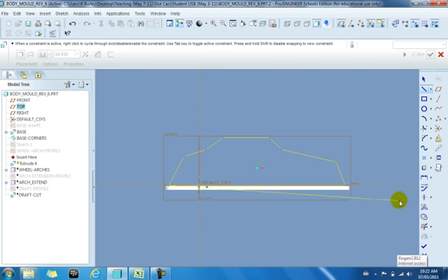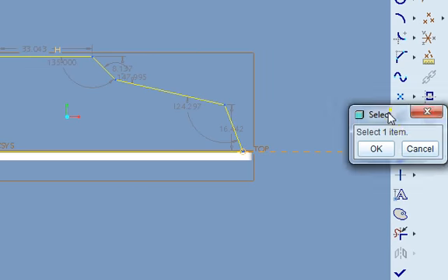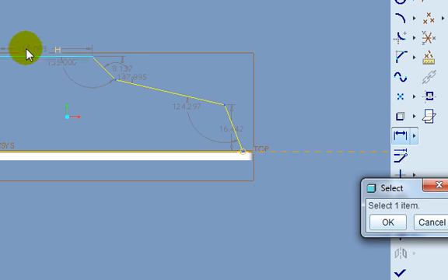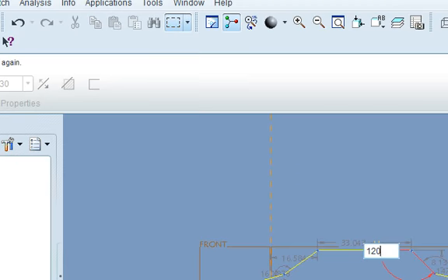Okay, now what I do is I click this button. You see the button I clicked right there, and it shows you all the dimensions. Now you can go and change things. We just did the rough sketch, but we can change some dimensions. Maybe I want to change this particular angle at 135 degrees. Maybe I want a different angle. So I'm going to double click that one and double click that number, and change it to 120. So that changes the angle.